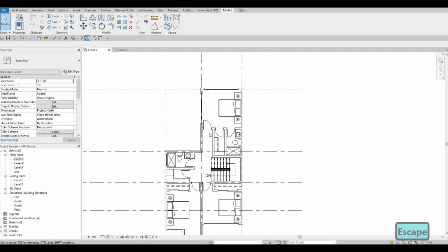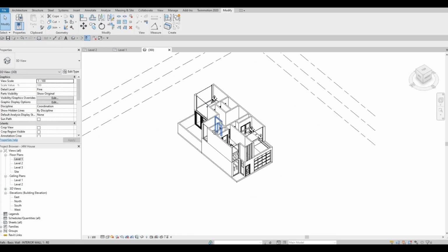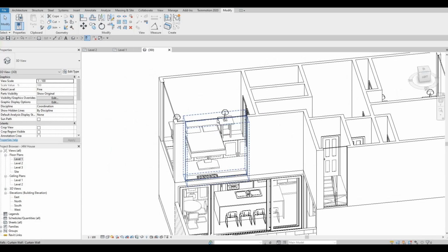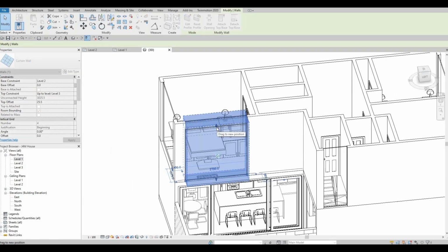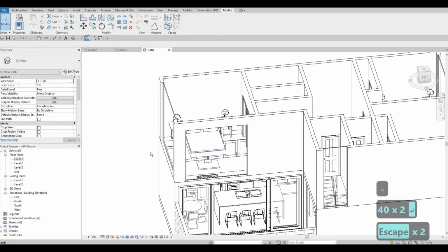Now let's go further and let's go to our 3D. So go to your 3D, and then here we're gonna set the height that we want. So most of the time around -400. I'm happy with that. And then after that, AL, align on all of them.